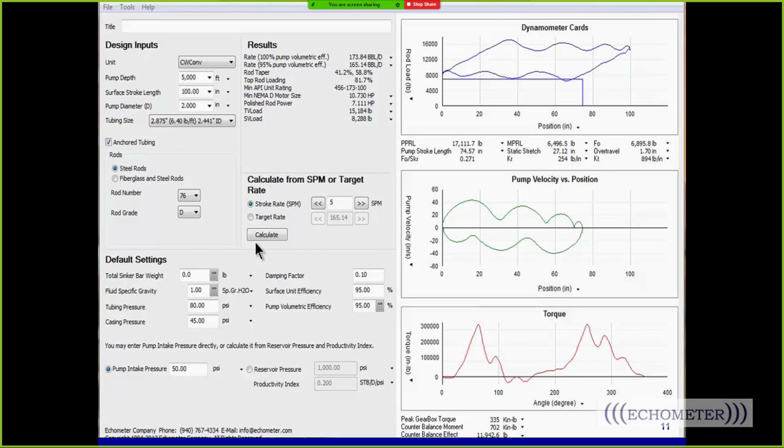So the paper that Carrie Ann wrote on tubing anchors can block annular gas flow talks about setting the anchor below the perfs, and there's a good discussion in that paper. So there's a lot of decisions that you have to consider when you're talking about running a tubing anchor.